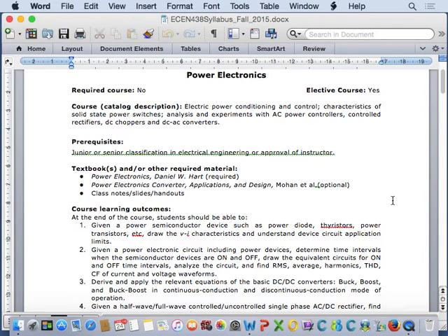We will talk about the effect of frequency on sizing electric machines and generators a little bit, and you will see that the higher the frequency, the smaller these apparatus are. So your transformers become a little bit smaller. Your electric machines become a little bit smaller when you do that. Of course, the lower the voltage, the safer it is. Of course. So it's a safety versus economics versus historical inheritance sort of thing of the system, a mix of things, right? We'll talk briefly about that later.